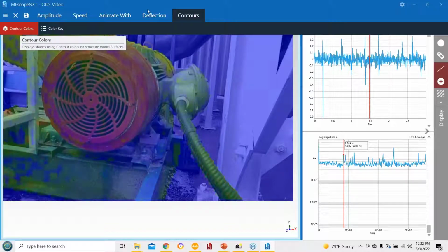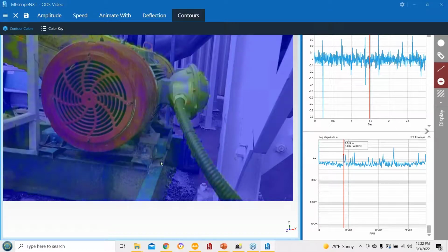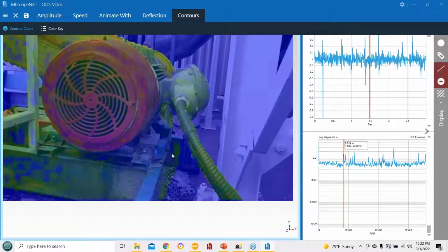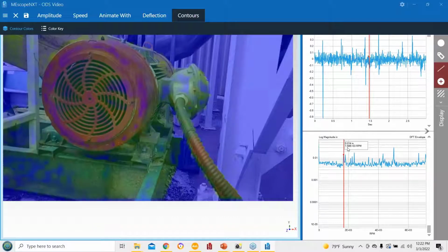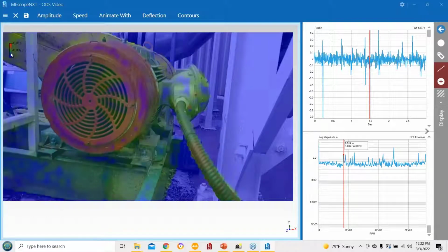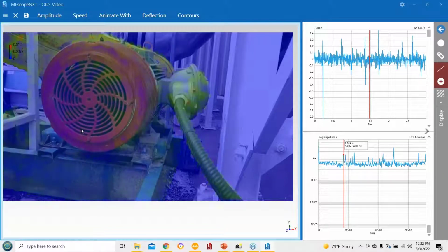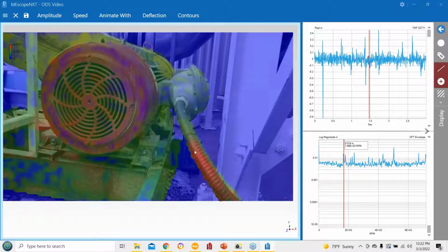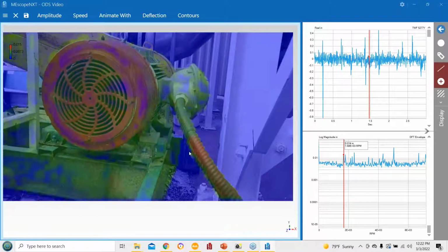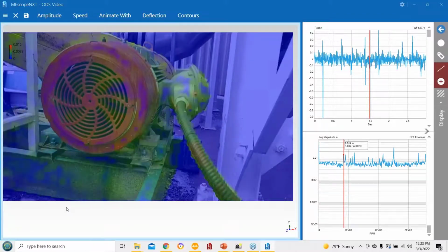Everybody out in the audience, if you've taken data before, you're taking it horizontal, vertical, and axial somewhere, trying to get as close to the bearing housing as possible when you take that data. You see big vibration, the dominant vibration, and if that's my color key, bring it down here. If I have the highest vibration, this is in inches, so 15 thousandths of an inch, that's probably this. The really high vibration is not where you're measuring all the time. It's stuff like this. It's the sheet metal buffeting, all kinds of things that you have to worry about now.